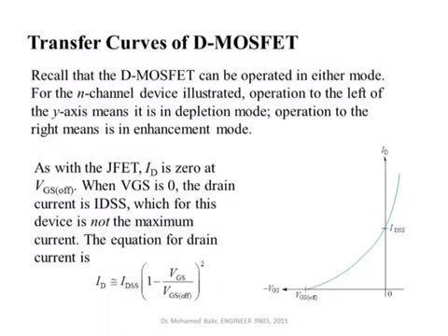So this is called D-type MOSFET, and as I said, it is naturally on. It has already an N-type channel, but we can deplete this channel. We can deplete it by applying negative voltage up to a certain value, and then beyond that value there is no conduction channel, and then the conduction will terminate.